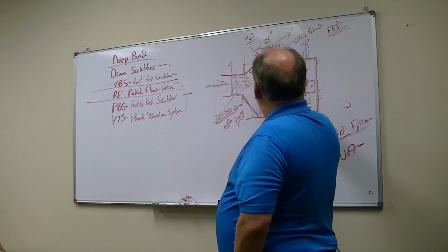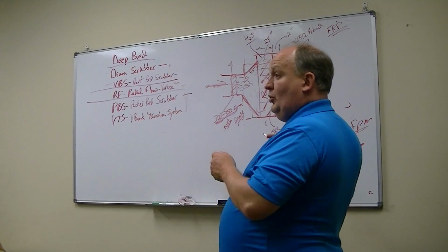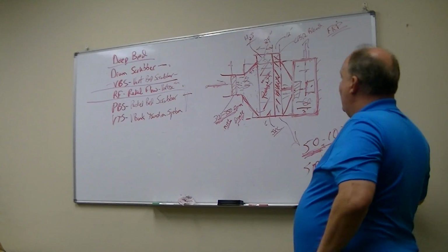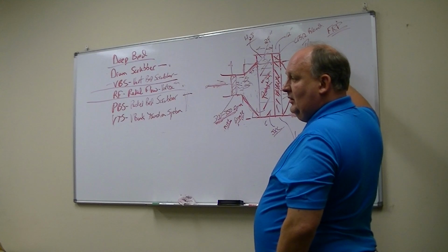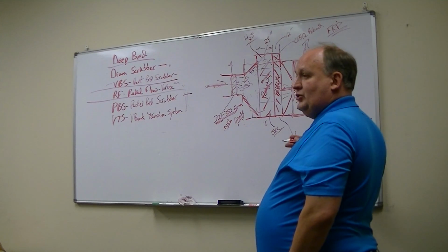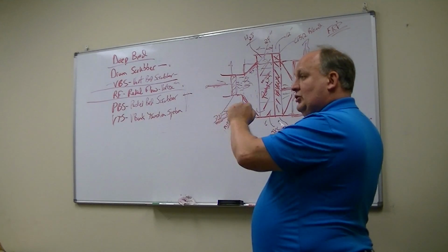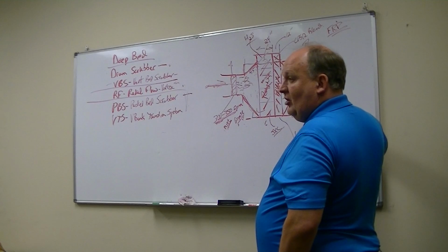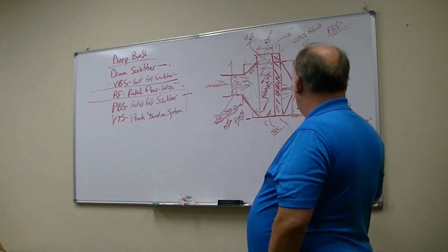Everything here is under vacuum, but this one's under pressure. So if you put a door on there, especially a big door, suddenly you've got some pressure. It's not a tremendous amount of pressure because you're pretty much just exhausting out this chimney here, but there's some pressure there. So you need to allow for that in that door. You need a really secure way of latching that door all around in a number of different spots, and make sure the door is nice and rigid as well.